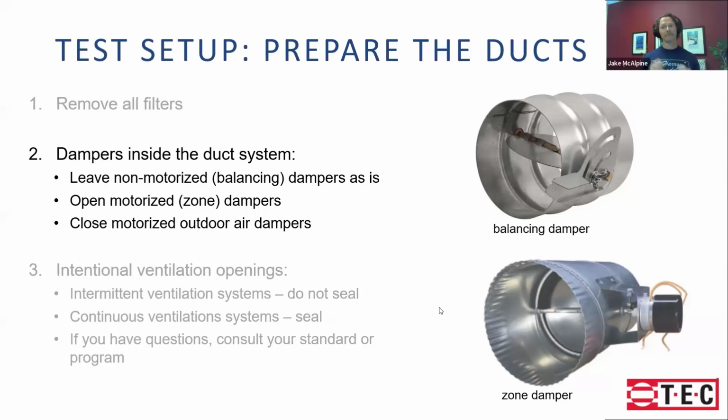Now, if we have something that looks kind of similar, with a fairly similar design approach, but we put a motor on that and actually zone or damper off an entire portion and have multiple thermostats and have a zoned system, we want to make sure those are open. Those are actually going to act like a filter. If those are closed while you're doing your test, similar to that filter example, all the leaks downstream of them are going to be artificially measuring low because you're not going to get that uniform pressure. So zone dampers, you want those to be open.